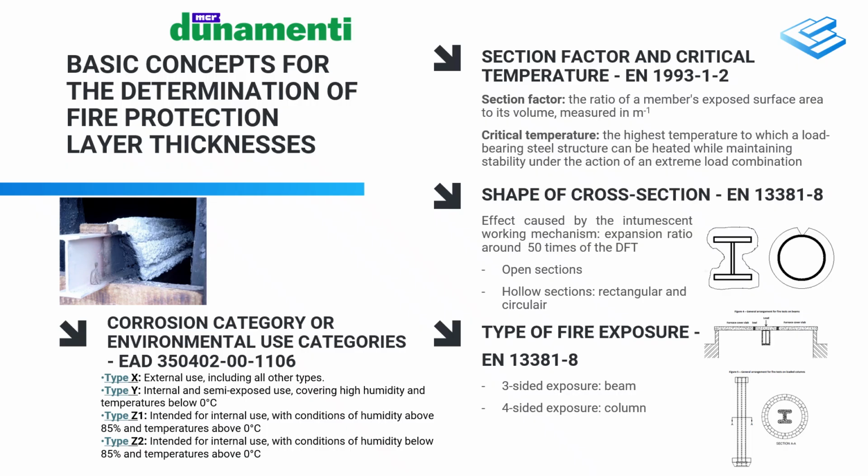The critical temperature is determined by a mechanical fire analysis, which specifies the maximum temperature to which a structural element can be heated up without losing its load-bearing capacity. The higher the critical temperature of the structural element, the thinner the additional thermal insulation layer required in the event of a fire.